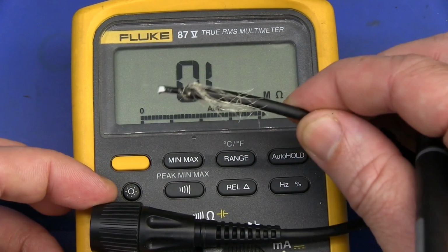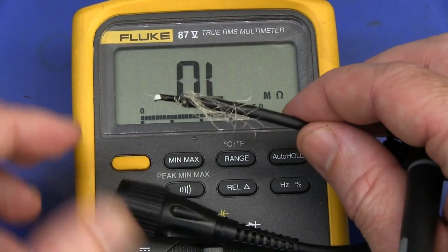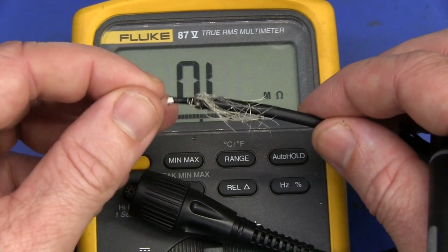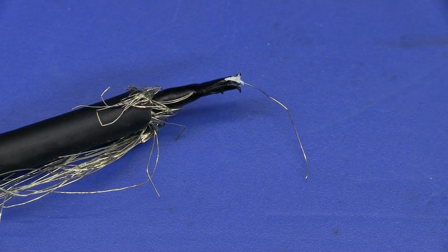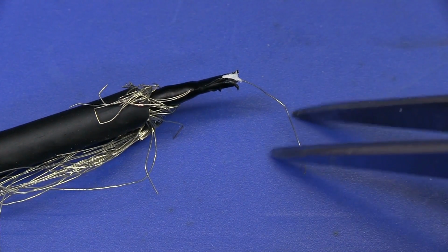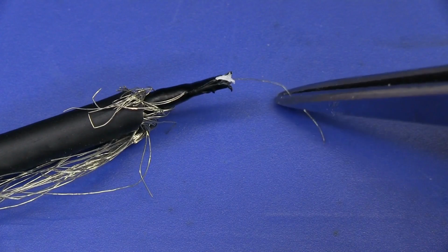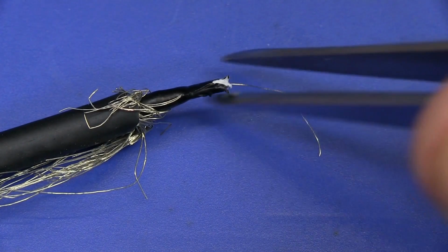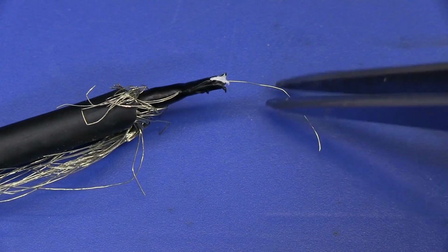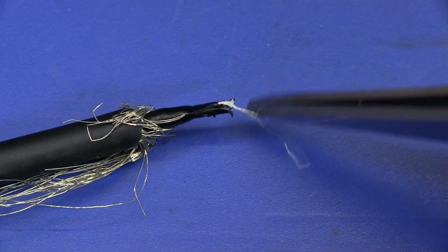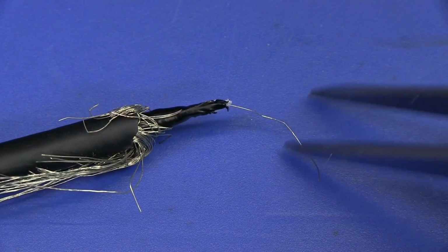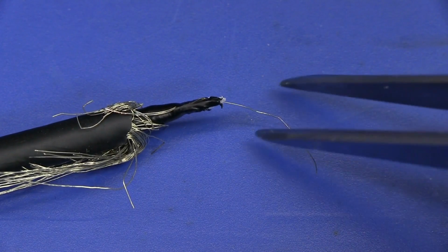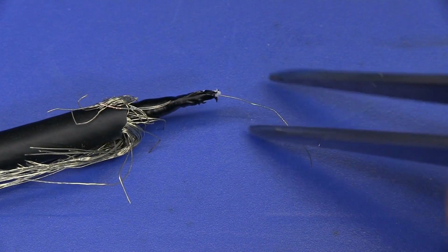Oscilloscope probes do not use regular coax like a regular coax cable. These are what's called a lossy transmission line. They're designed to have that high resistance. And check it out, that's what's inside an oscilloscope coax cable. It's a single strand there. No, I haven't actually, when I stripped it, I didn't accidentally cut off all the other strands. It is a single tiny strand like that, and often you might be able to see that it's actually not entirely straight. It's actually got little kinks and bends in there, and that's actually designed in some of the higher quality ones.